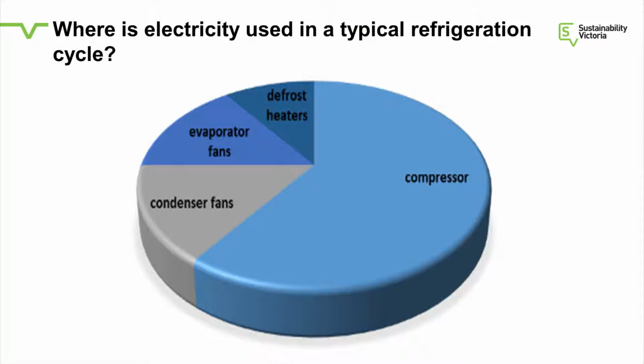of money in terms of energy to generate refrigeration, and about 20% of that is just used to make ice. Right? It doesn't do us any good. It just makes ice in your fridge, or it makes ice in your cool room. And then we have to spend more money on more power to defrost that. This doesn't happen in your home fridge, it just defrosts by itself. But in a supermarket or something, there's actually electric heaters in there which melt the ice back down again. So you pay for the ice twice, when you make it and when you melt it.